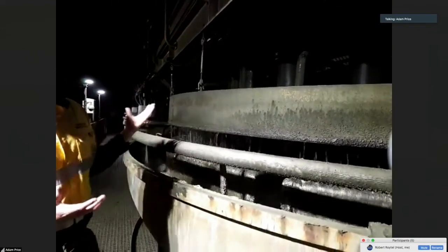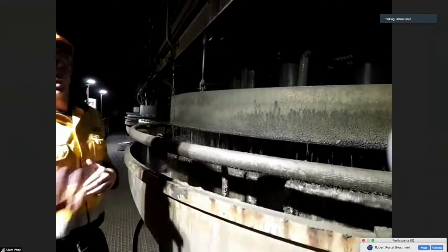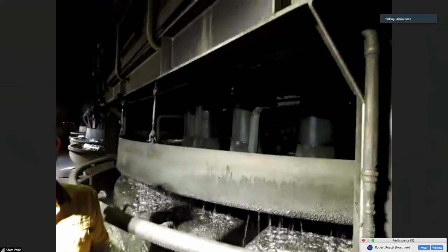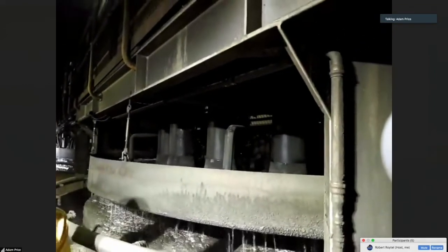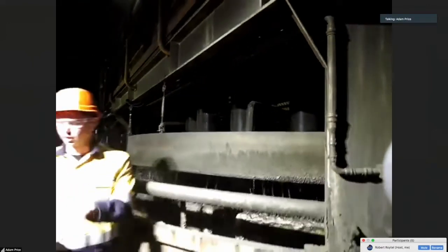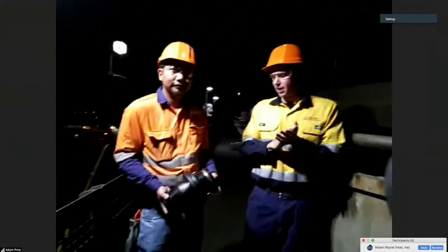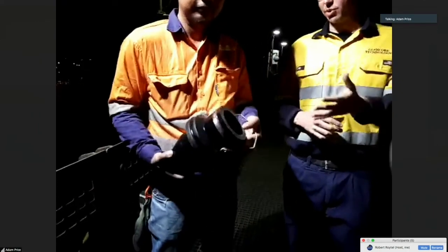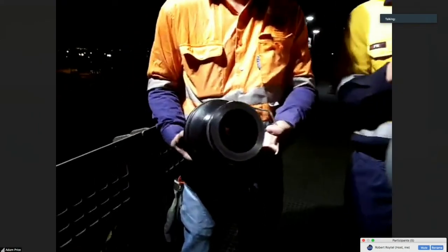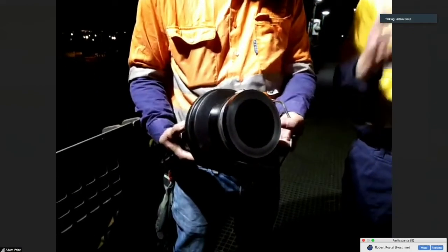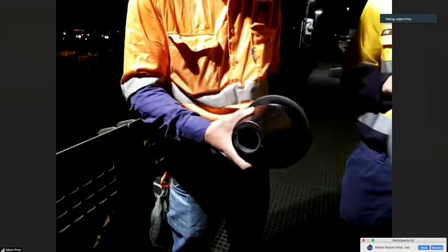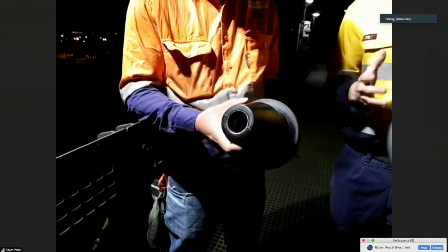And then right at the top of the downcomer, we have the slurry lens orifice, which is the real key part of the equipment. I'll just get Christian to quickly show you a little bit of a look at the slurry lens orifice there while I keep talking. But essentially what will happen here is this will create pressure within the top of that system. The slurry will get turned into a high pressure jet. And this is a real key to the technology.